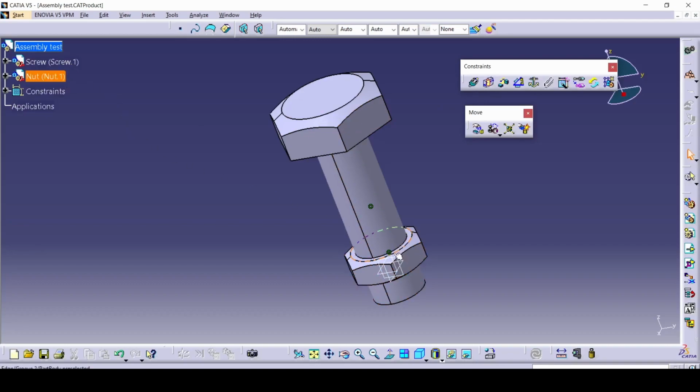Now that we've done this, you can see these little constraints. That's the coincident constraint. They will be made in the constraints bar in our little tree right here. So be sure to look at this because sometimes you can maybe add multiple same constraints and it's going to give you a little yellow triangle saying that's a little bit of a mistake. You're confusing CATIA. We can't really go on because of that little error.